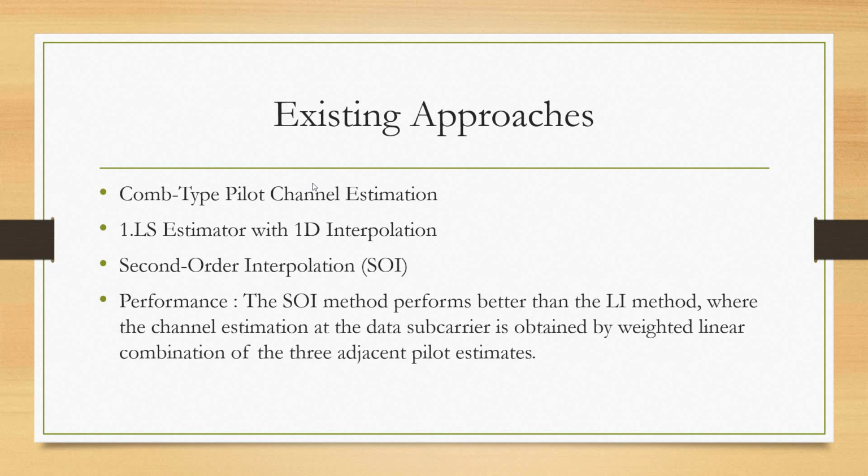And the second-order interpolation is called SOI. The SOI method performs better than the LI method, where the channel estimate at a data subcarrier is obtained by a weighted linear combination of the three adjacent pilot estimates.